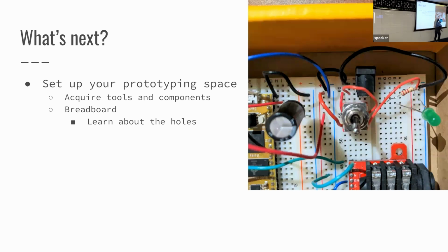And basically you've got power coming down here, so if you take a wire coming out of any of these, you can get a ground connection from one of these, or a power connection from here. And then each of these rows, you can connect things in series or parallel based on configuration. It makes more sense when you're actually looking to set up a circuit. But I also explain series and parallel.